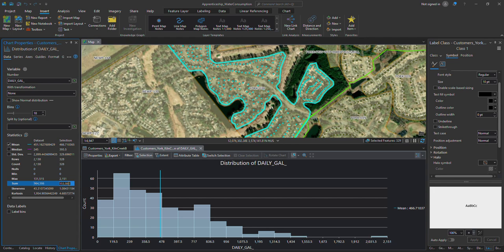So with this calculation, modelers or engineers can determine the necessary flow for pump stations, the necessary size of pipes to handle this flow, or potentially treatment plants to accommodate for an additional connection that pulls this flow area to a new pump station and treatment plant. So the information we calculated here can be used for many different uses and can be put in reports. And this is just one example of how we utilize data spatially here at HRSD.